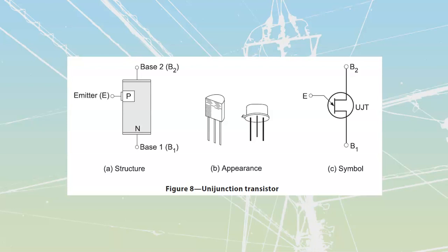Okay, next one that we're going to take a look at is called the UJT. The UJT is a unijunction transistor, and the name does not mean actual transistor, because transistors are able to be used in an AC format for amplification or increasing the amount of current. Tiny amount of base current results in a large amount of collector current, right? We've done that thing numerous times.